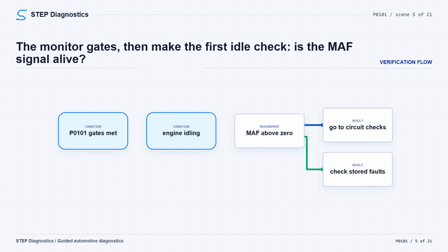Engine coolant temperature, -40 to 117 degrees Celsius, 130 to 266 degrees Fahrenheit. Engine speed is 560 to 1000 RPM. Intake airflow valve position, greater than 85%. MAP sensor is 70 to 130 kPa, 10 to 19 psi. And vehicle speed, less than 3 km per hour, 2 mph.